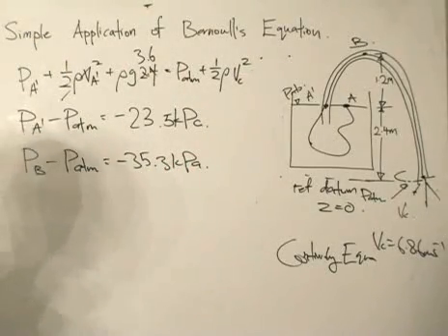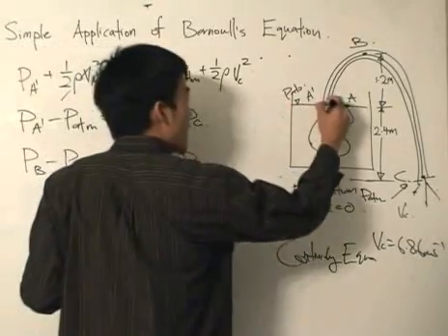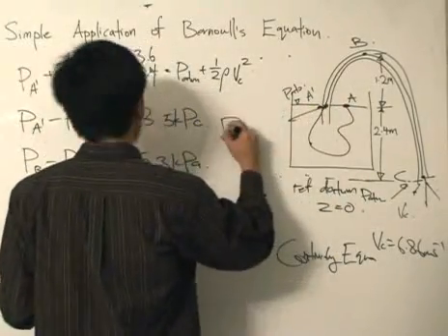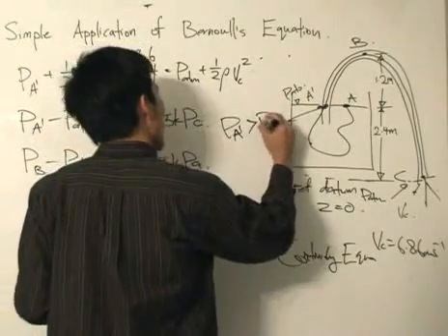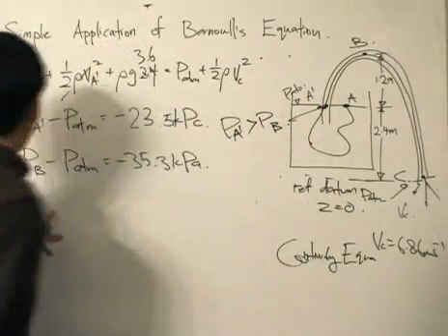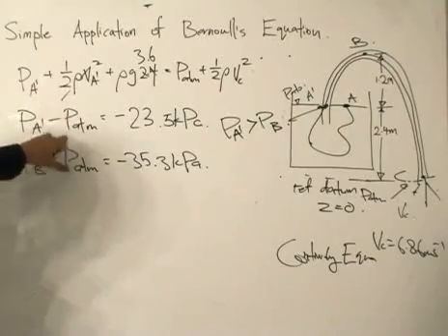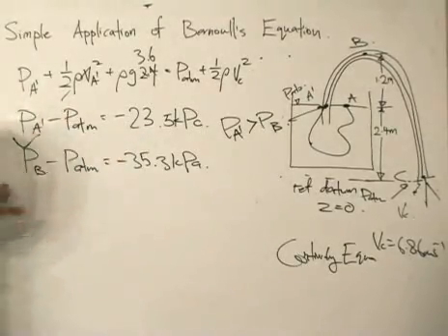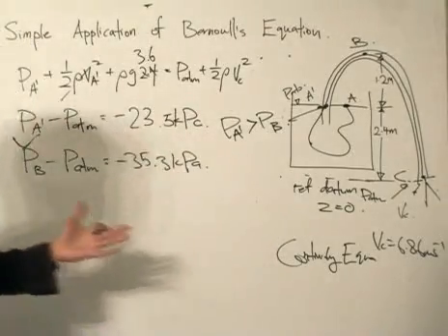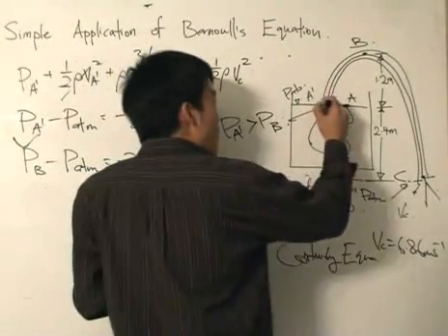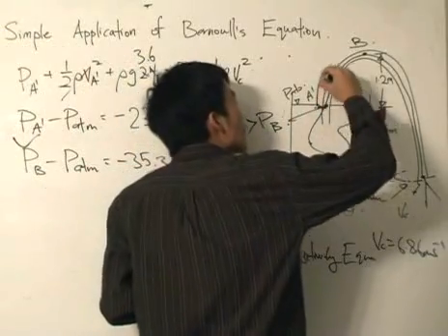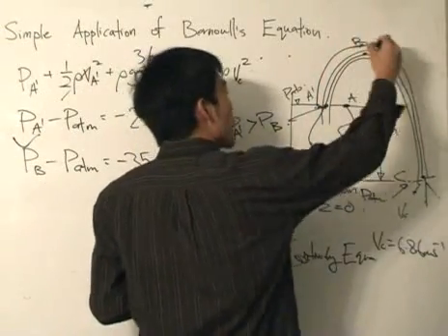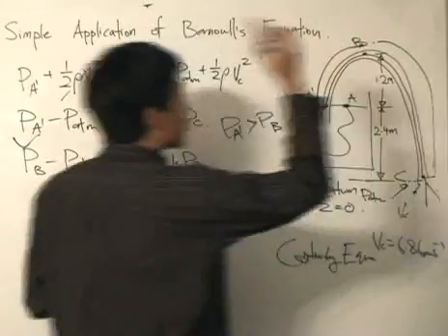Observing it carefully, notice that the pressure at A dash is going to be more than the pressure at B. That means when we subtract the same value, we get a less negative value. So this one is going to be more than this, if I write it like that. And this explains the siphoning effect. Because it's the higher pressure that is able to move the liquid all the way to point B, after which the effects of gravity will move the liquid down.